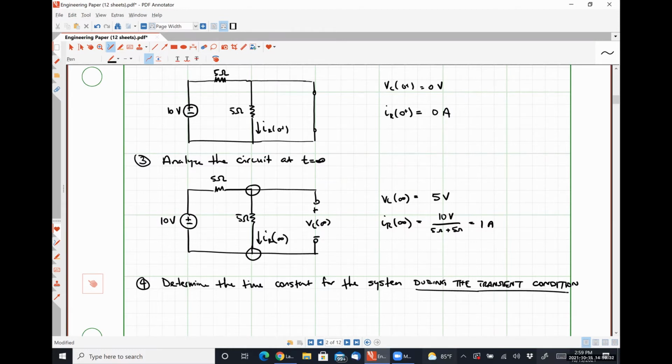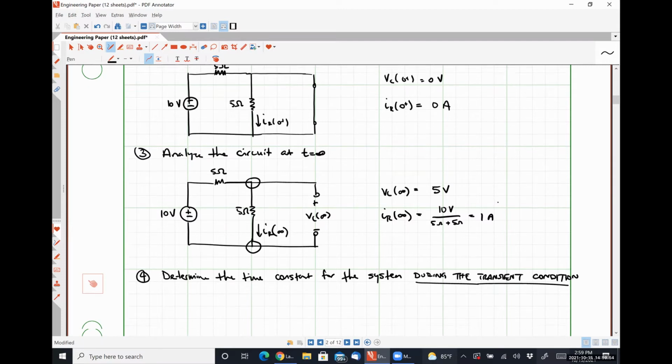So we're going to calculate our time constant in the exact same way that we determined things on Wednesday, okay? For this particular problem, there's only one capacitor, so I feel pretty strongly that we can all agree that the equivalent capacitance is C equal to 100 millifarads. Am I okay with that? No, hopefully no room for argument there.